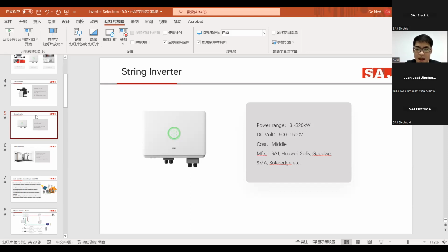In the IEC standard and the US safety code, the regulations require that only voltages below DC 1.5 kV and AC 1000 volts fall into the low voltage range.